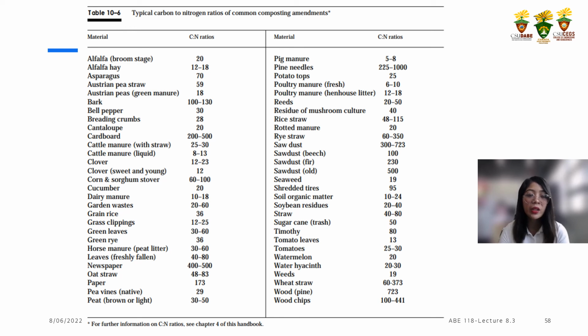So, pH is self-regulating and is not a concern with composting of agricultural waste. Bacterial growth generally occurs within a pH of 6 to 7.5, so it should not go below that range. So fungi growth usually occurs within the range of 5.5 to 8.5. The pH varies in the compost mixture during the various phases and can produce putrid odors.